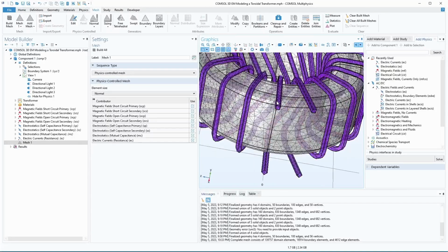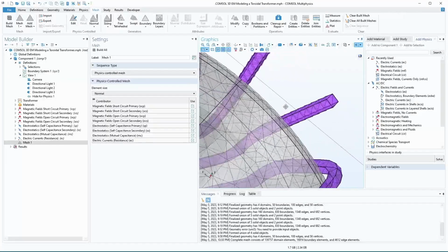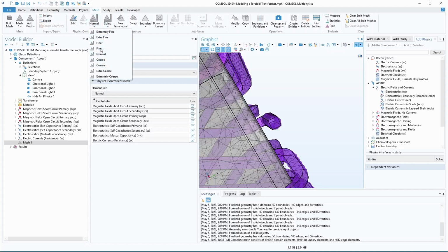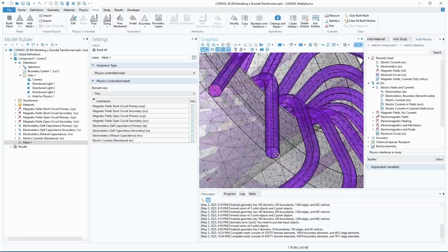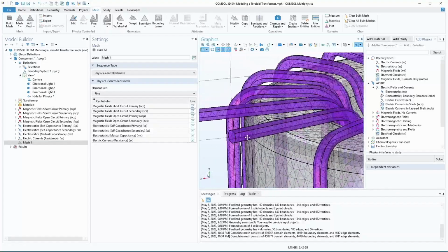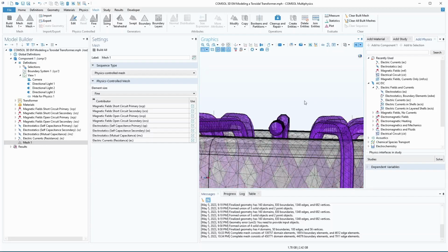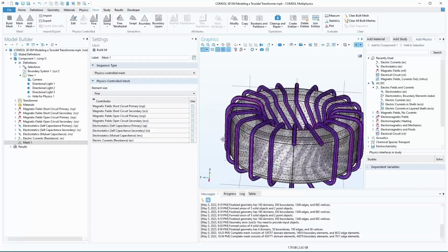These wires are not exactly squares, but they're kind of square. Maybe they're octagons. Anyway, I think for this, I'm just going to do fine and try that. Okay, so there you can see what fine does. Fine will make the simulation take longer, but it will make more accurate results, and will also help with convergence. So I think I'm just going to do that for this one.